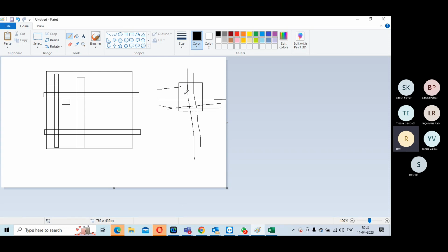This power pin, which is supposed to connect to the top level, should be exactly underneath the top mesh M12. That's when you can easily drop a wire. Otherwise you'll add another extra route causing congestion. So floor planning with this is also important. The tool will do something, but you will have to manually check whether these happened properly or not.